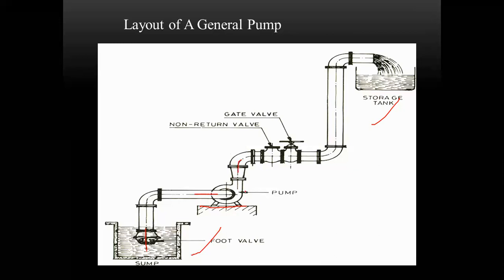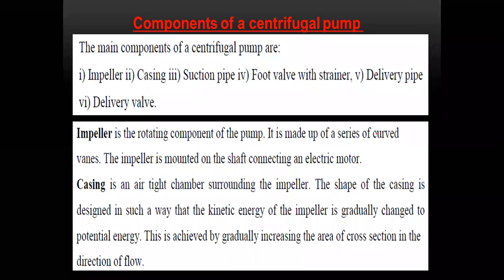Whenever you switch on, the motor rotates, the shaft rotates, and the shaft is connected to the impeller shaft, so the impeller rotates. The water goes into this pipe, and through these valves you open and close, you can decide whether the water discharge, the water flow, will be high or low. The water goes in this direction and you fill your tank. This is the general layout of any pump. Simply remember it.